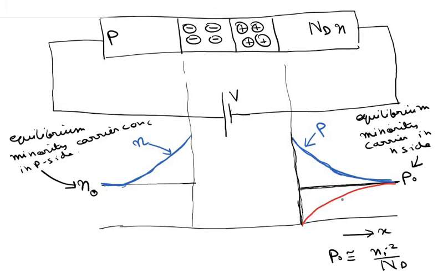during reverse bias. Okay, so just outside the depletion region, this is actually for holes, which are basically again minority carriers in the n side. So just outside the depletion region, the concentration of holes is actually 0, because no holes are actually diffusing from the p side to the n side. During reverse bias, the potential barrier has increased, so no holes are diffusing from the p side to the n side.